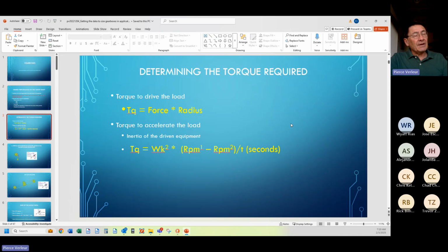which means the higher T is, the lower torque is, which translates to the longer you have to accelerate a load, the lower the torque required to accelerate. The shorter the amount of time you have to accelerate the load, the more torque required. Drag racing is a classic example. If you need to get to the quarter-mile point as fast as possible, you're going to apply the maximum torque.